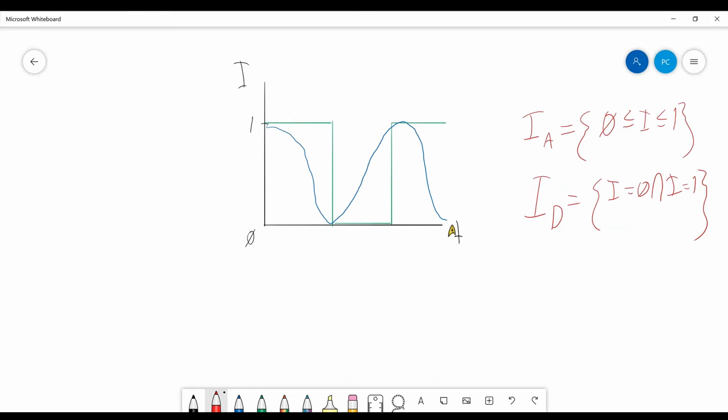The computer inside the microcontroller interpolates the analog signal and produces a value between 0 and 1023. So you see, this is what is going on when the Arduino is sensing an analog signal.